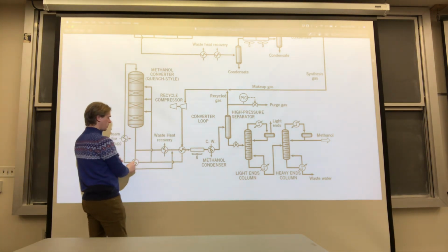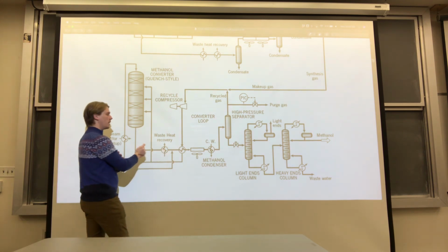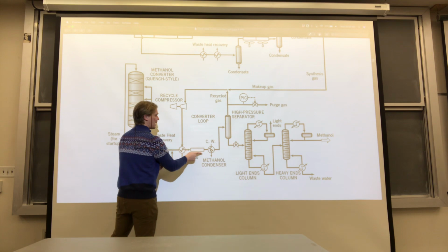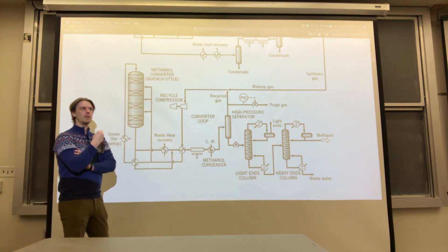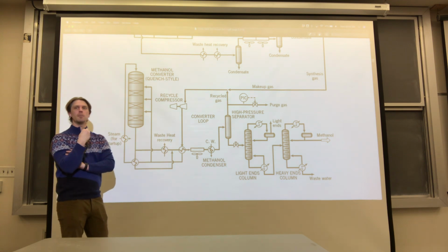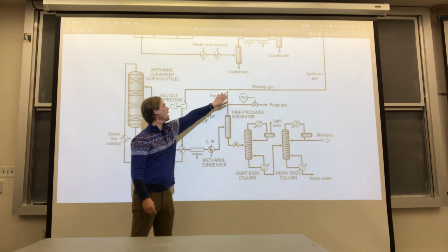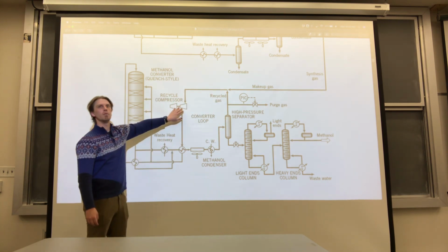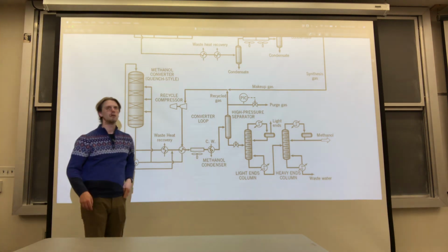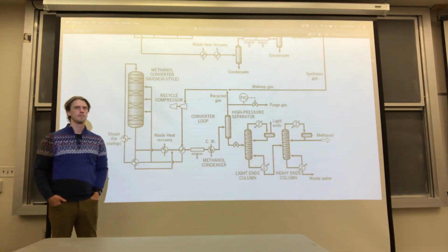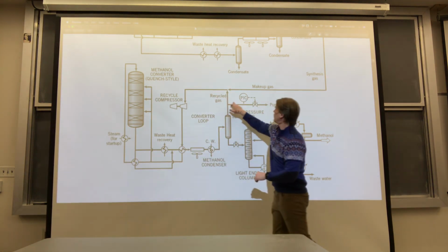So we're using the energy, we're collecting some steam here as well, right? Then we're going through some fans and some cooling water to drop the temperature further, such that the water and methanol will be able to condense inside of the flash separator. Then it goes back, it gets recompressed, repressurized. This heats it up a little bit, and then we get more energy back through each of these individual streams. Then we have our recycle with the purge.